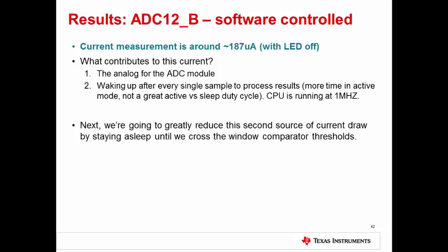When using this basic way, the ADC is using tons of power, but it's not as good as it could be. The CPU is not only wasting time triggering the ADC, but doing the comparison in software. So next, we're going to make a program that does the same basic functionality as this one in a different way, but using lower current.